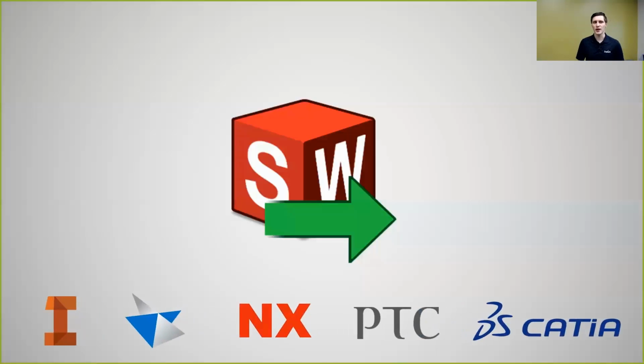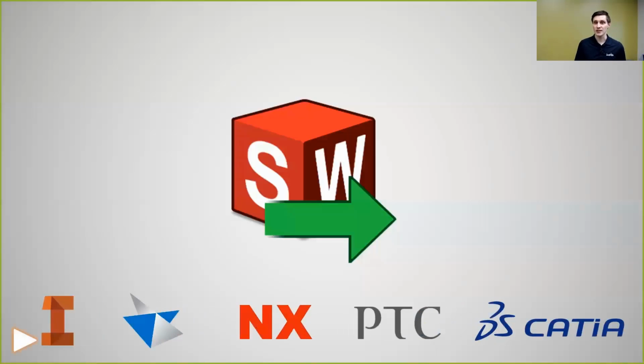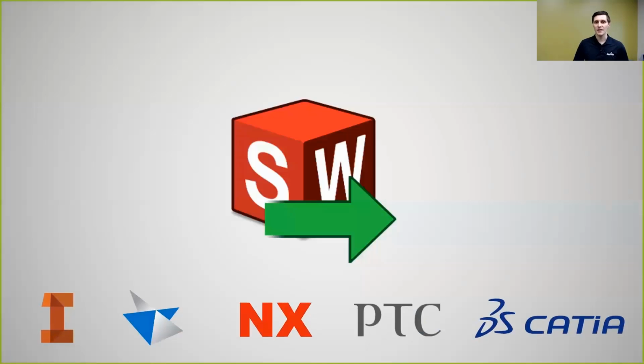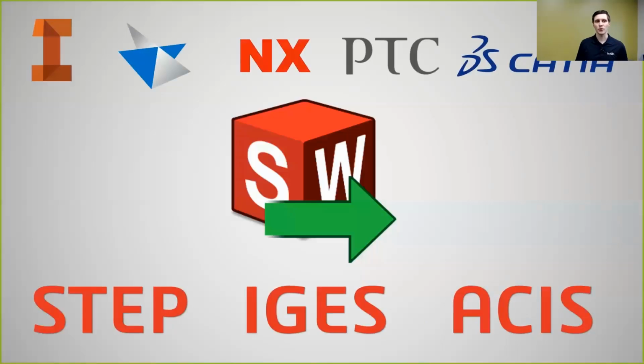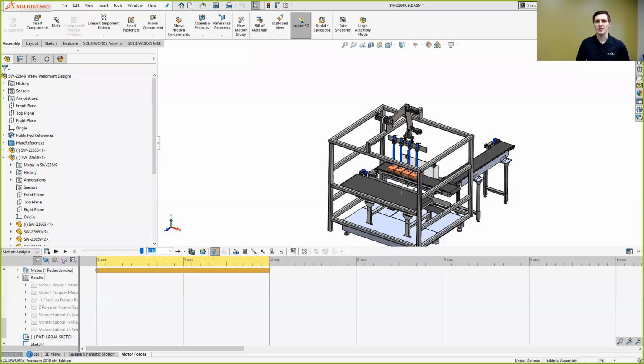So to do that new spec, we're going to use 3D Interconnect. It was introduced in 2017, and then in 2018, we now have multi-CAD, or we have support for STEP, IGES, and SAT files. So it's going to give us a really powerful and easy way to deal with native CAD geometry or translation geometry, and we'll see that here as we jump back into our assembly.